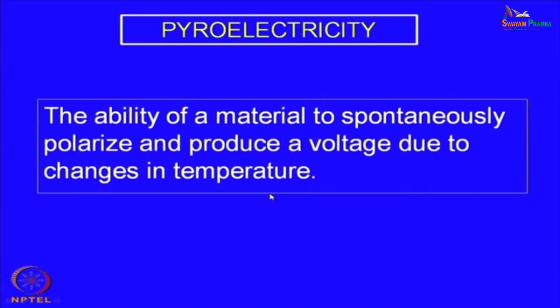One thing I forgot to mention, so far as the ceramic or the piezoelectric motors are concerned, not only are they miniature in size, but their torque is very high compared to the electromagnetic motors. The torque is very high at a much lower voltage, okay, and it does not of course make any sound, as it is very tiny and there is no electromagnetic effect.